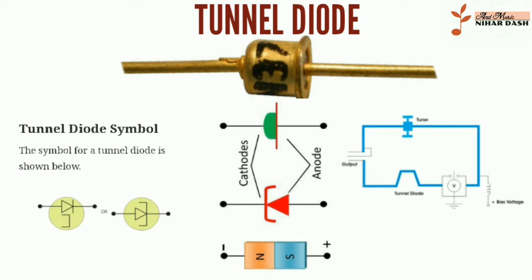The application of transistors in a very high frequency range is hampered due to the transit time and other effects. Many devices use the negative conductance property of semiconductors for these high-frequency applications. A tunnel diode is one of the most commonly used negative conductance devices. It is also known as an Esaki diode after Leo Esaki for his work on this effect.